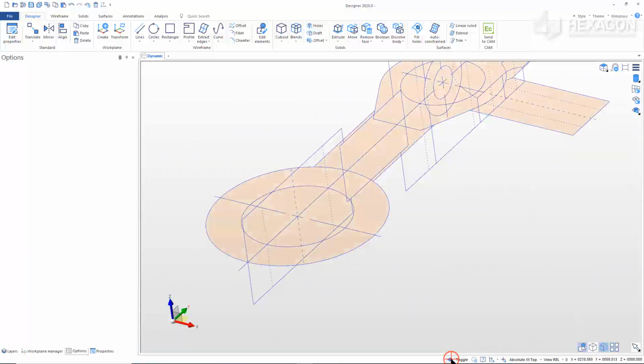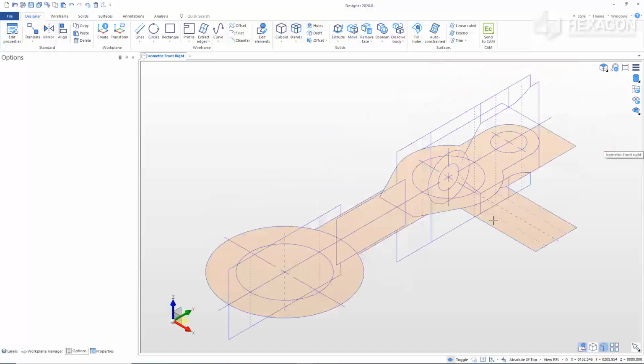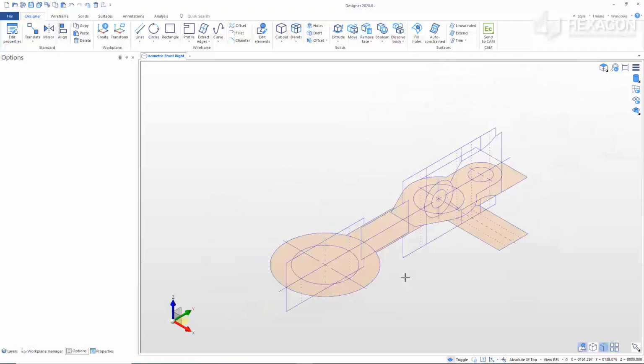Toggle Region Creation on from the status bar. When regions are on, we see a tan-colored temporary surface type entity in enclosed wireframe areas. These regions make it very easy for us to extrude those areas into solids.